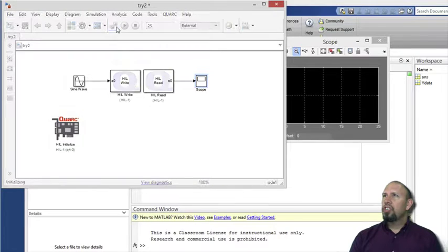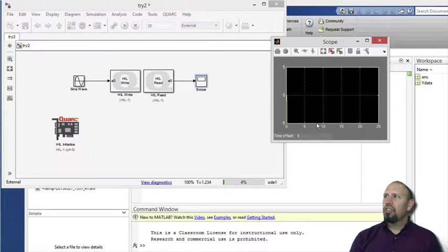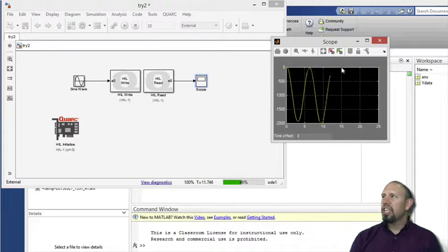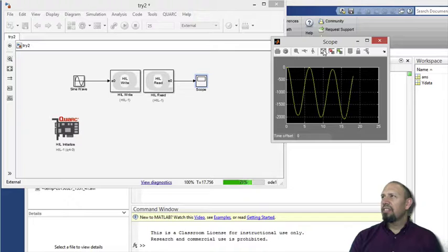So now here's the connect, and here's the start. Those are the two things I need to do. Now my process is running. I'm driving a motor with a sinusoid, and you can see how the output looks. Notice that these are large values because it's actually looking at encoder counts. It's not degrees, it's encoder counts. That's what it has. And you can see it's a sinusoid with a little bit of a drift. It's kind of drifting downward a little bit.